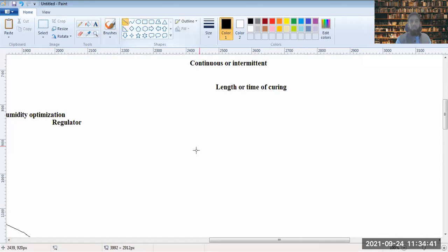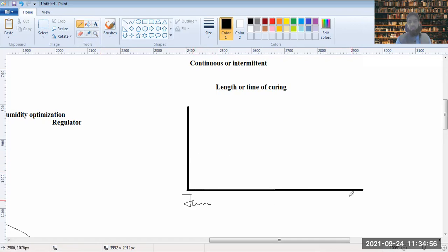It has been observed that once the strength comparison was made in different seasons, the lowest strength of concreting comes in if this is Jan and this is December, this is July. The minimum strength is in Jan, the maximum strength is in July, and December again it goes near to what it is in Jan. So minimum strength would always be achieved in Jan.